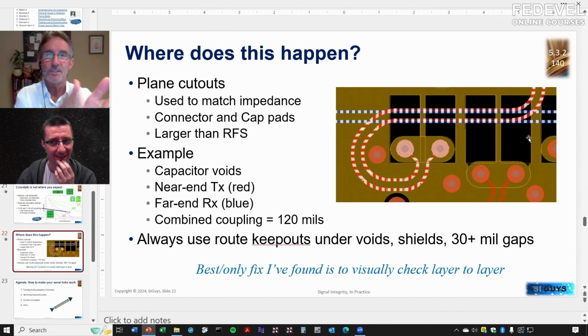But that is not what I would call simulation. That is physical, just dimensional shapes, types of checking, right? On the last slide I was doing waveforms, but you don't have to do that, right? You just have to design rule check this. Look on one layer, oh, there's a hole. Oh no, I have a signal just a few mils away on another layer, right?